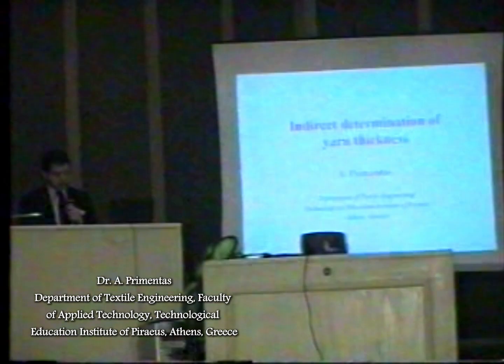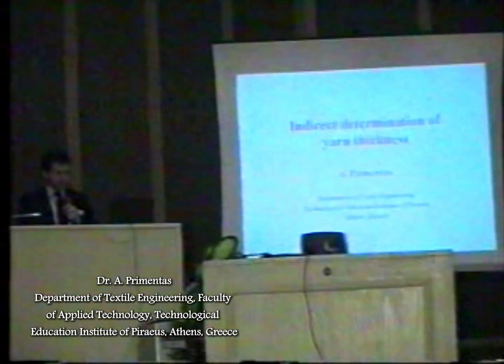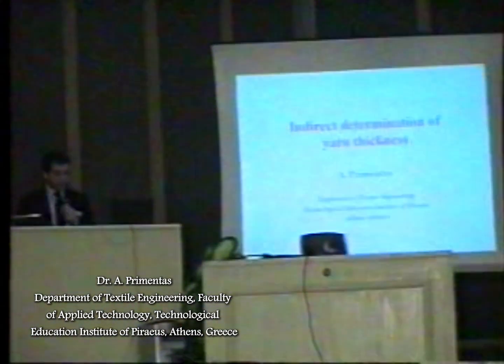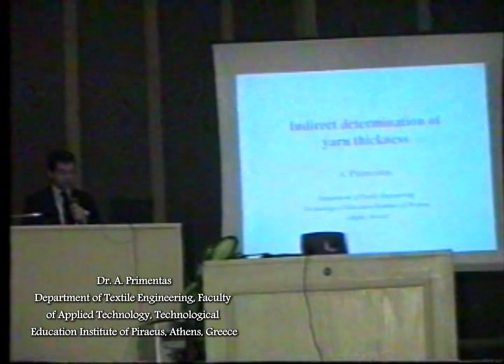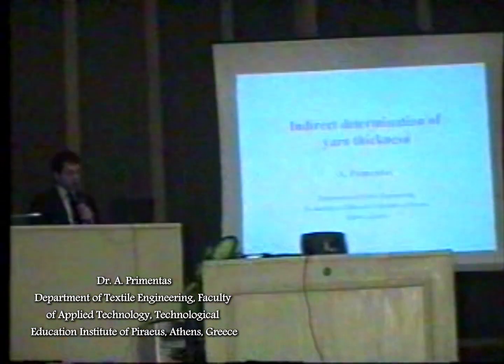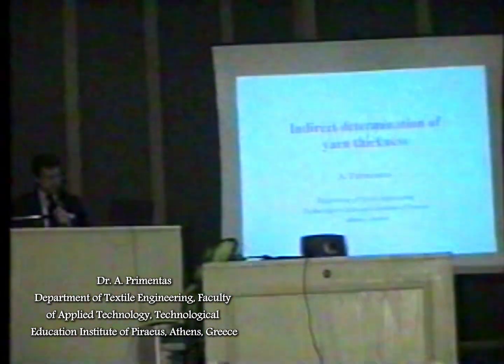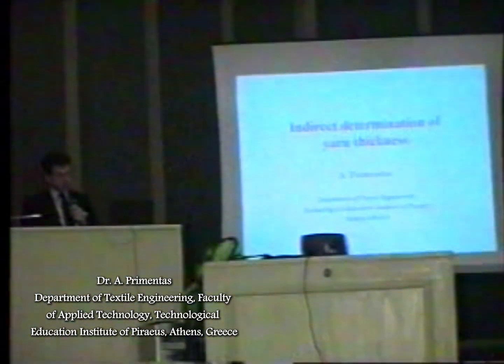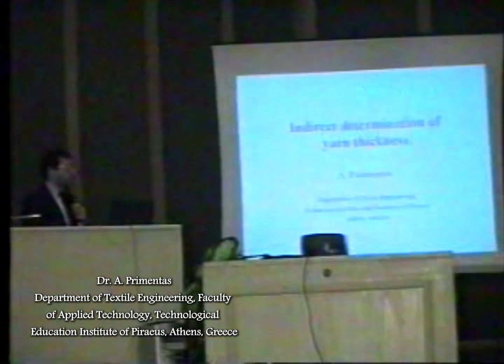The results of a series of experiments supported the derivation of linear regression equations relating yarn linear density, yarn diameter, and load exercised on the yarn samples under examination on a fabric thickness device. The obtained readings from this device are not far from the readings of the same yarns obtained microscopically.